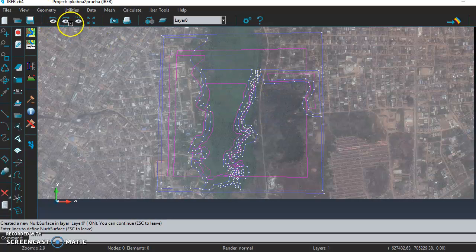Okay, surfaces. Next step will be creating a mesh, with different resolutions for every place of the city. We will give it as a parameter for the river and the floodplain, because maybe we don't need a 12 meters resolution in the city, maybe we need only like 15 or 20, but we will need a good resolution in the floodplain also, or maybe in this side of the city, because it is nearest to the river. And if we give different measures for the mesh, we will have a better flow analysis. The time of computation will be different. Okay, it will be faster if we give different values.